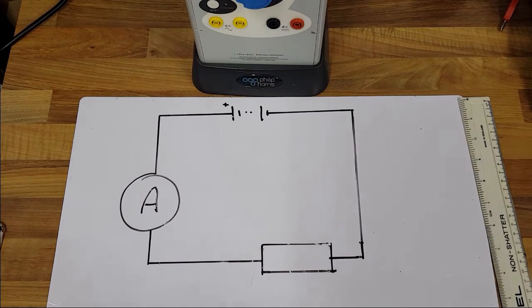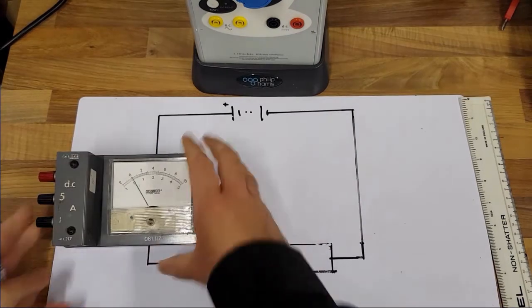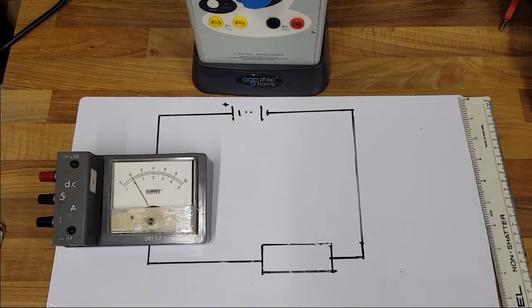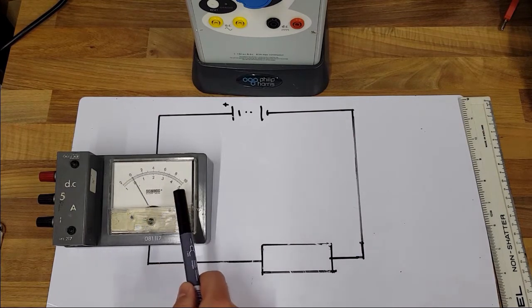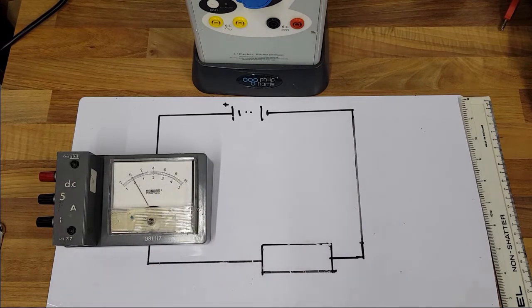There is a very good reason for that. Just like when we are actually building the physical circuit, it's always a good idea to leave the voltmeter until the very last minute, and then you piggyback it onto the working circuit. So let's start putting some of these components in place. This is my ammeter. It's got a range from 0 to 1, so where it says 0 to 10 at the top there, that is going from 0 to 1, so 8 will be 0.8. Okay, so that's my ammeter.